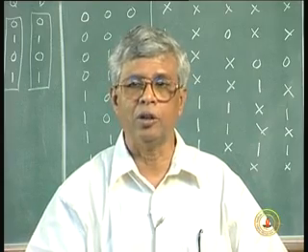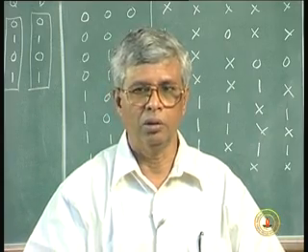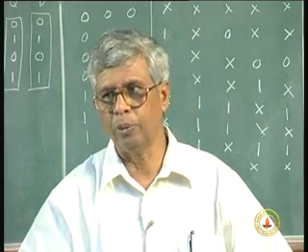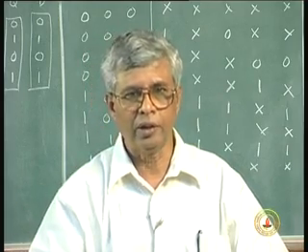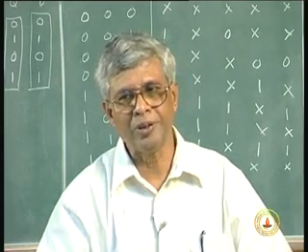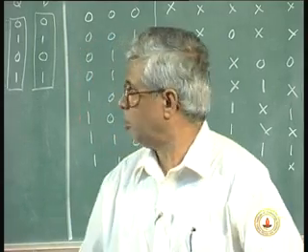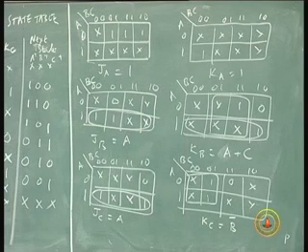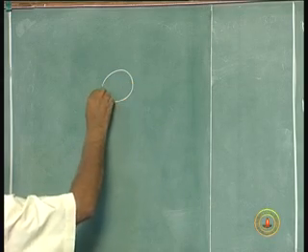That is the generalized model we drew in the beginning of this module of lectures on state graph implementation. You have external inputs along with the present state inputs, which are taken into account to design the external outputs and the next state outputs. So, you can always modify the state graph with external inputs. Let us draw a simple example of a state graph which will also have external inputs. I think we drew a similar state graph in the beginning.